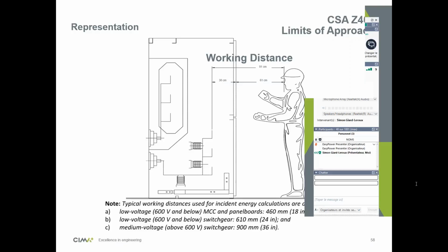I think I got some precision about the genset. The person wrote that they mean out of the IEEE short circuit range. Yes, the IEEE 1584 standard has a defined short circuit range for its model to apply. So if the short circuit current for your genset is lower than the minimum, the method can't be used to calculate the arc flash energy.